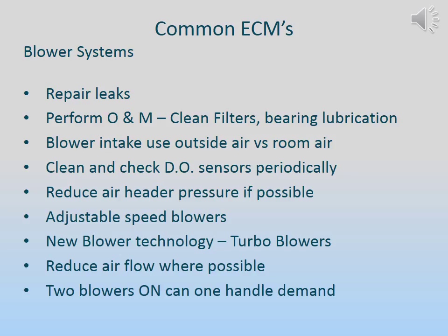For blower systems, make sure leaks are repaired, and typical O and M tasks such as cleaning the filters and bearing lubrication are performed. The blower intake uses outside air versus room air. Is it possible to use inside air since it should be a clean source? Clean and check the DO sensor periodically. A lot of places have a laboratory instrument that they use for calibration checks of their field instruments periodically.